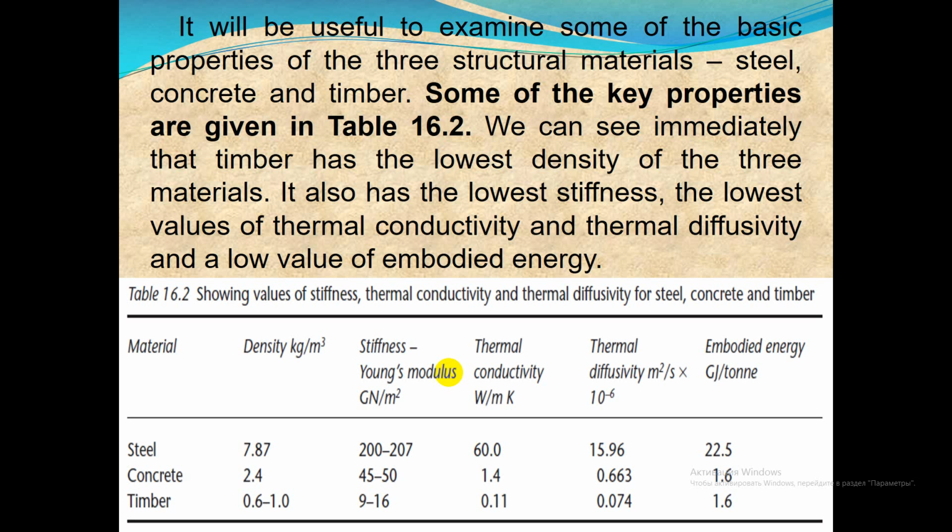Timber lends itself to machining and pre-cutting of the piece of timber, and of doing some prefabrication under factory conditions. On-site work is then limited to assembly of factory-made units and items. And this leads to more accurate construction and to a considerable reduction in the time spent on site.